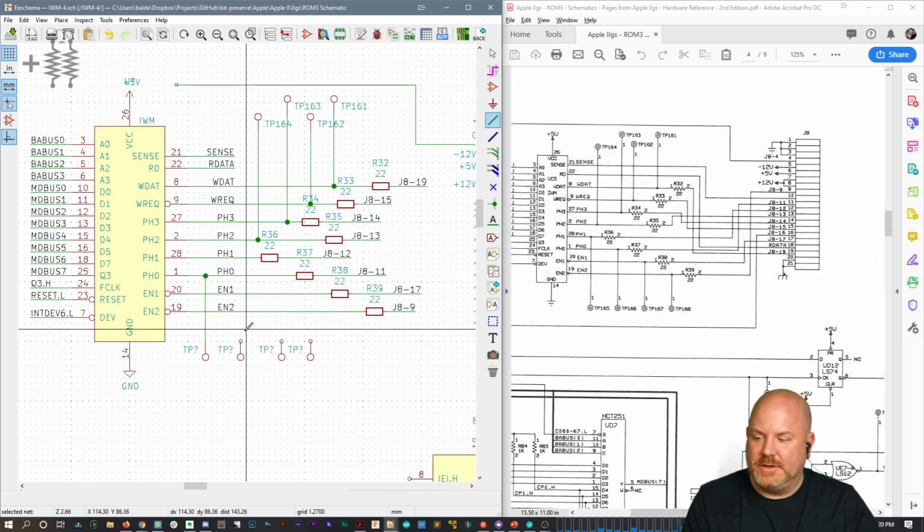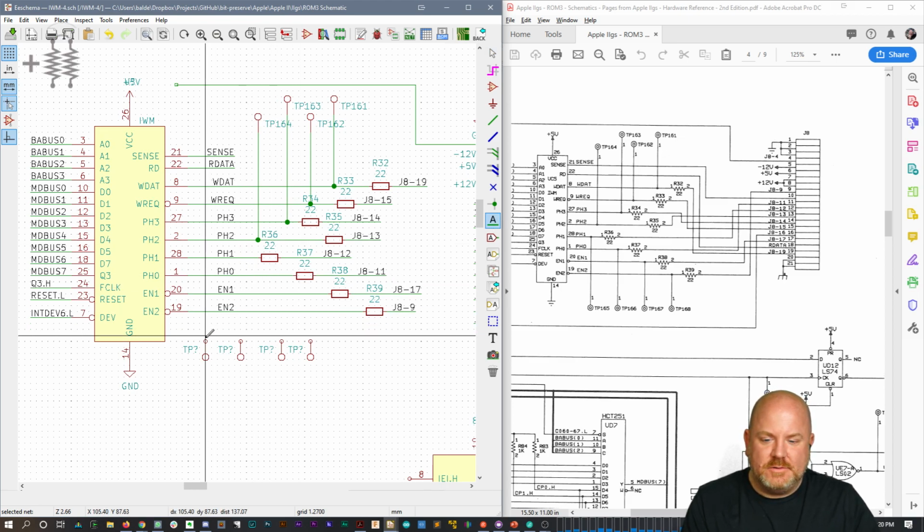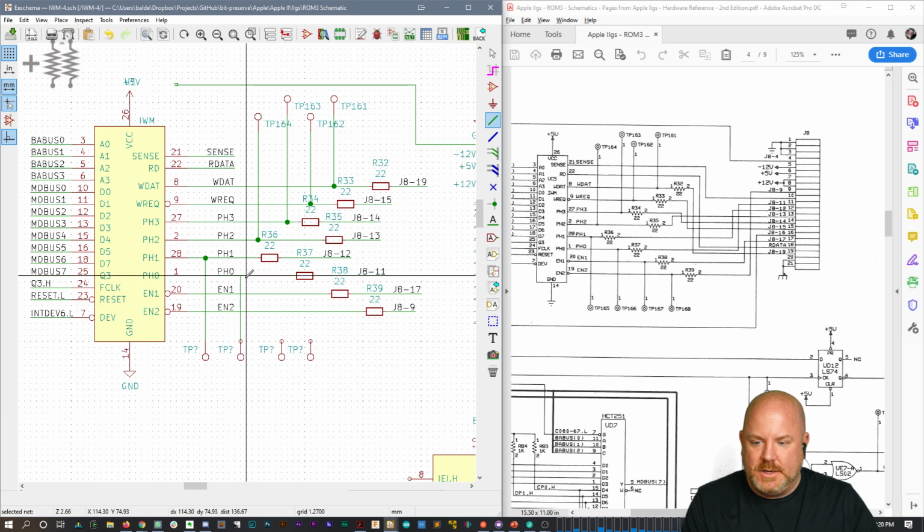But I think you should be able to. Oh, no. I guess you really couldn't, because how would it be connected to the pin when there's no power? So that wouldn't work at all, would it? I was thinking what you're going to end up measuring is whatever the protection diode on the pin is. That's going to get activated when it's powered off.